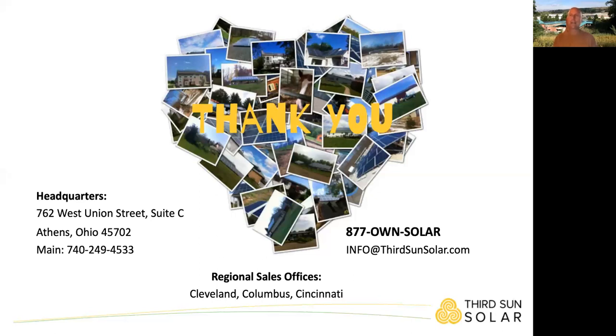So we have a hybrid. We have a utility interactive system, but we have many clients. We just finished wrapping up an install for a 100% off-grid client. To be off-grid is certainly not for your average customer. There's some people that want to do it. They're ready to have that responsibility of keeping a closer eye on their primary source of energy, which customers that have the utility and solar don't have to do. And they have a generator. They almost always have not just batteries and a large solar array, but they always have a fossil fuel fired, usually propane, backup generator as part of the system.